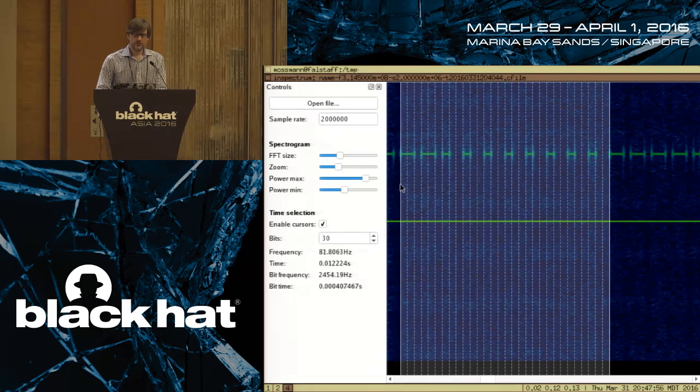There, you can see that it's about 2,450 bits per second. That's what Spectrum calls a bit, based on the period that I have specified here. Really, I would call that a symbol, right? I have 3 symbols per bit, and my symbol rate is about 2,450 symbols per second. So it's about the speed of a 2400 baud modem.